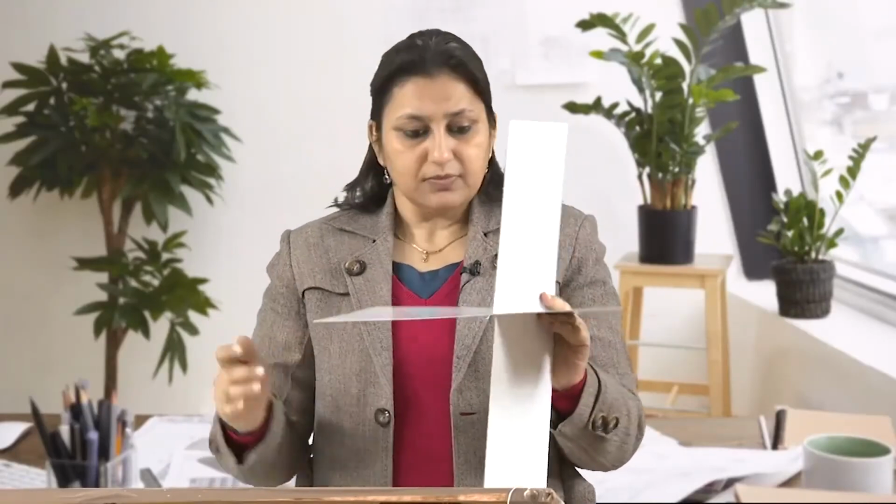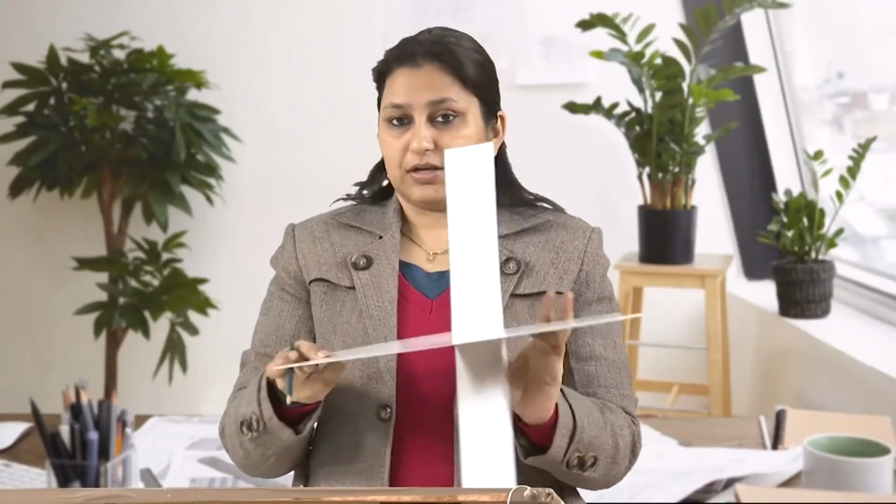Now, let us move on to second and fourth quadrant. So, assume that this same point which was at 50 mm from VP and 70 mm from HP is now located in the second quadrant. So, if the point is here somewhere, what happens if we fold it? Both HP and VP have gone to the same place. So, now in this case, we will have nothing below the XY line, the reference line. Both the planes, the HP as well as VP, have merged together to go to the top.